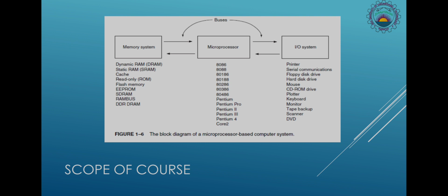And in the instruction set of the microprocessor, there will be some instructions to access input output devices or systems. So the same is the case here. The microprocessor will generate an address, and that address will be of a particular input or output device. That device will communicate with the microprocessor, and all the remaining input output devices will remain in idle state.